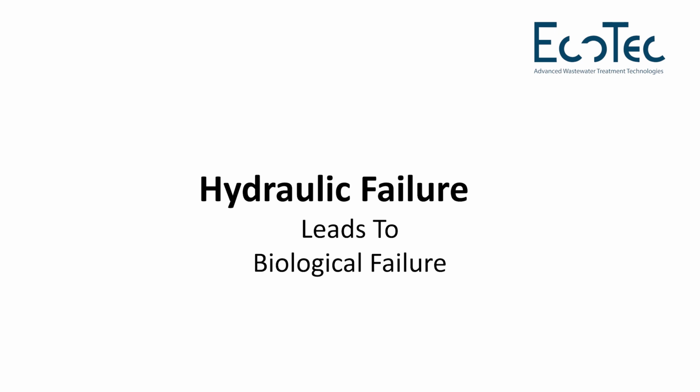Having seen the weekend influence, let's understand something a little deeper. There is a hydraulic failure because of not having understood the right peak factors. This again leads to biological failure in the sewage treatment plant due to various reasons. But there could be many reasons for failure of sewage treatment plants that are designed taking wrong peak flow into design consideration. We'll have this discussion in a later presentation, but let's stick to the hydraulic parameters alone now.